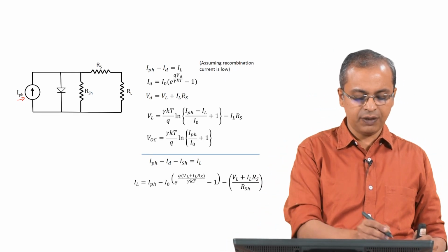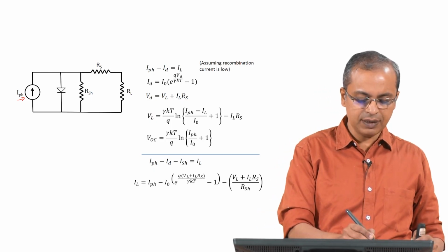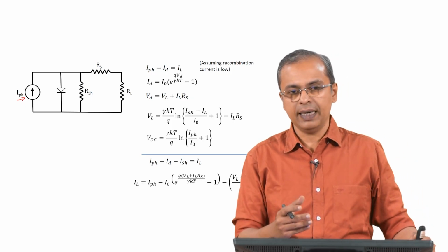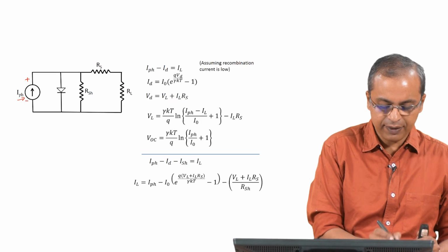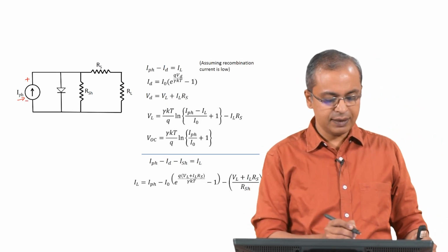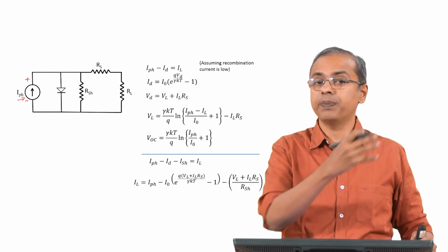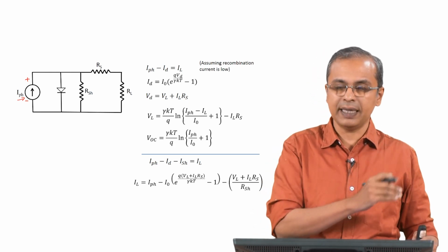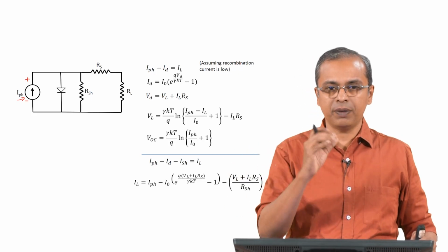So you have positive charges heading off that way, and this is the same diode, so you have positive on this side and negative on this side. Internally it is a diode, and so when you build up more positive charges on the P side and more negative charges on the N side, you have internally forward biased the diode.